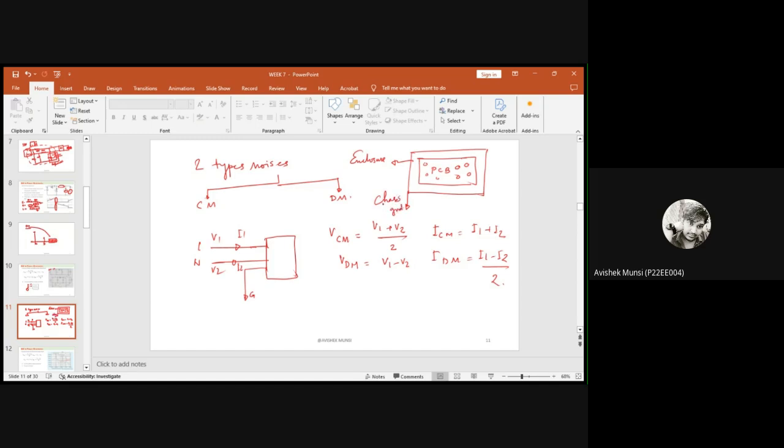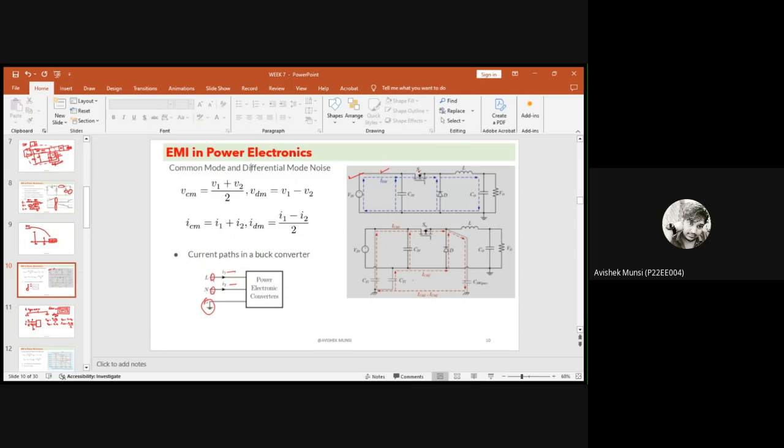The common mode noise, the common mode current, is generated due to this chassis ground, because in the chassis ground there is a metallic enclosure which we use, and all the other references which are connected into your circuit and your board inside the enclosure are commonly grounded to it. This is called chassis ground. So this chassis ground will create the common mode problem.